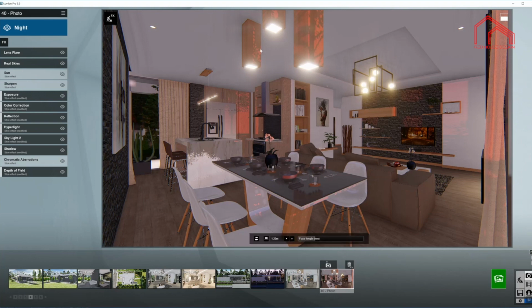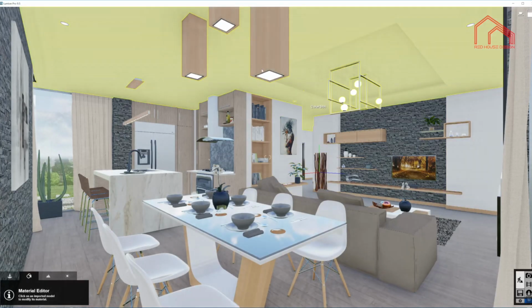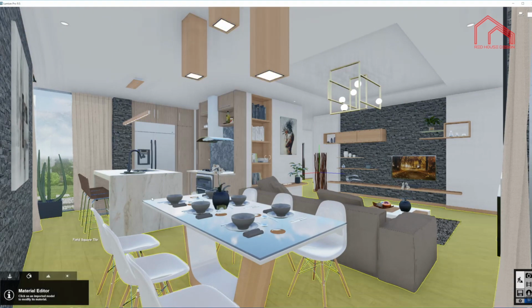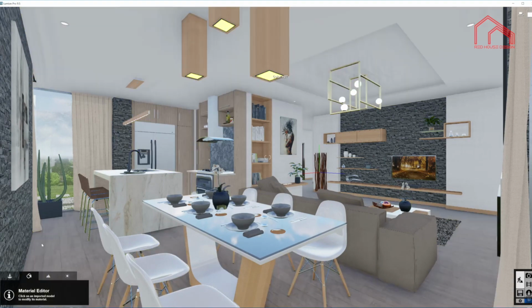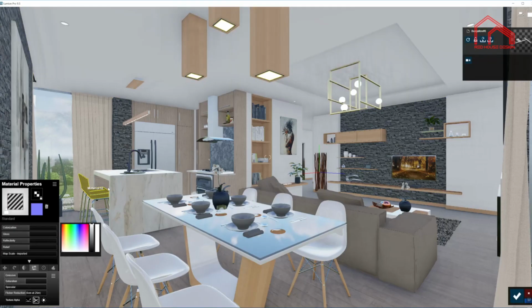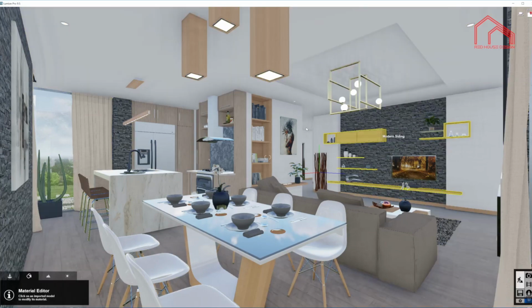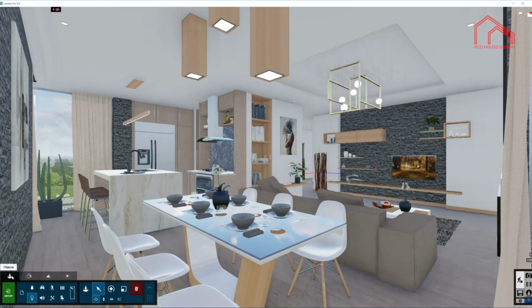Now, as you can see, a couple of materials are already emitting light in here. I'll show you how to do that. You just basically go to the Material tab, you click on a particular material that you want the light to be emitted from, or to behave like a light source. And down here in these settings, you go to emissiveness, and when you move the slider you can see the change in the material. So I'm gonna keep it somewhere in here. Confirm, and we can return back to our Objects tab and start working with our lights.